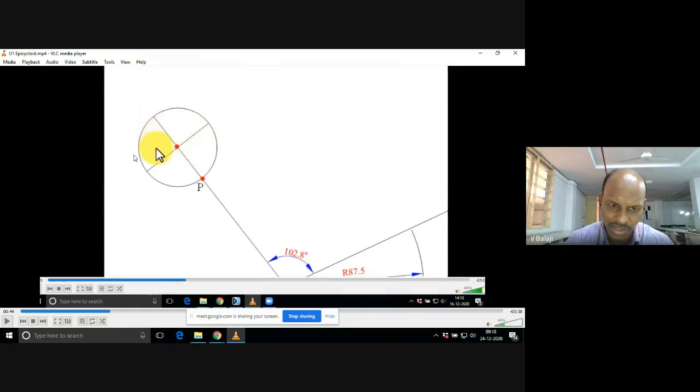Immediately after drawing the circle, along the same line, you will get one diameter, right? Perpendicular to that, you draw one more diameter line. Then you can easily divide this into 8 equal parts. Take your protractor, take 45 degrees here, here also take 45 degrees. In that way, you can divide the circle into 8 equal parts. Okay, this is important. So are you clear up to this?